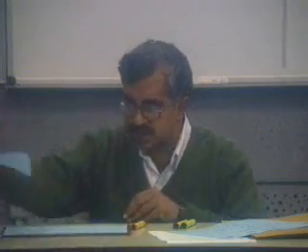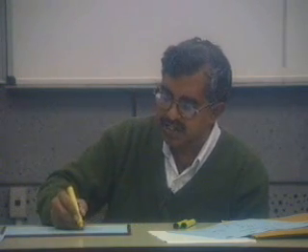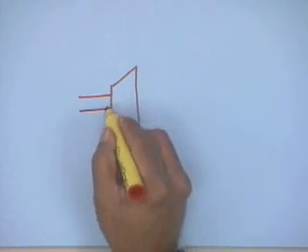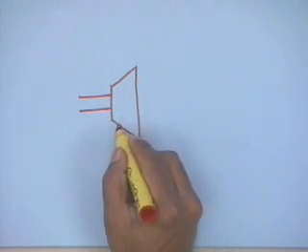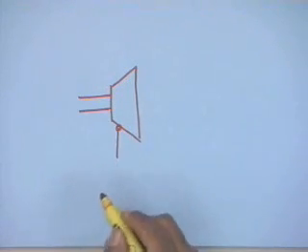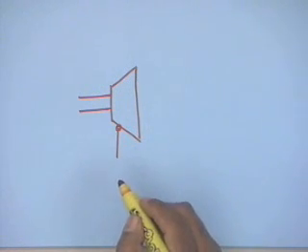So here I want to also talk about one thing: when you talk of decoders as practical circuits, or when you go to the lab and look at decoders, you have the inputs, but many of the time you may have enable inputs shown with a circle over here, which essentially means that this input is active low.